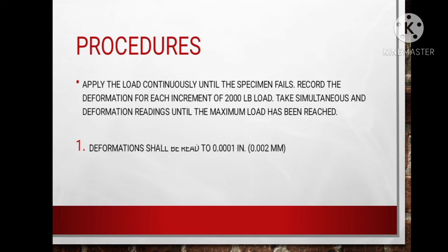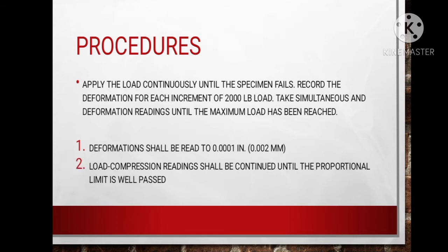First, deformation shall be read to 0.001 inches or 0.002 millimeter. Next, load compression readings shall be continued until the proportional limit is well passed.